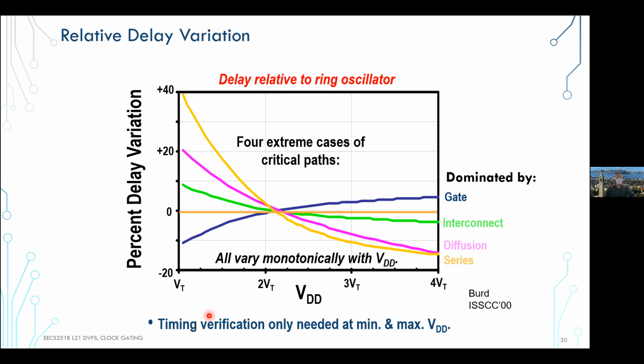For example, there's another paper from earlier on that really shows this. You design an inverter chain with different properties affecting the delay. As we all know from 251A, if you write the Elmore delay for an inverter chain, you have a mix of RCs: a gate-dominated term, R wire, R1 of the inverter.